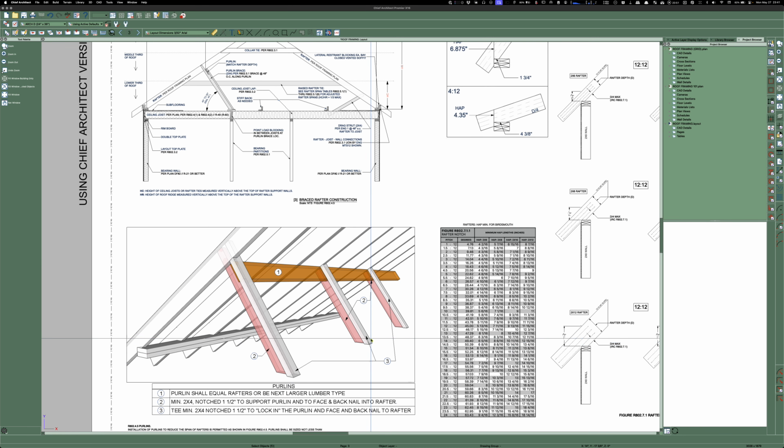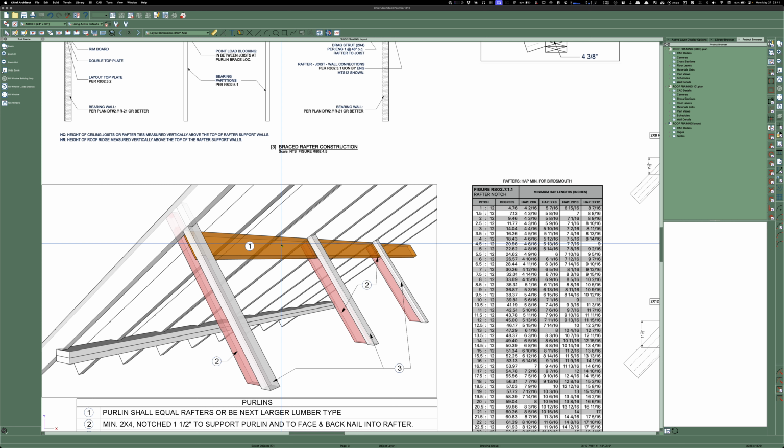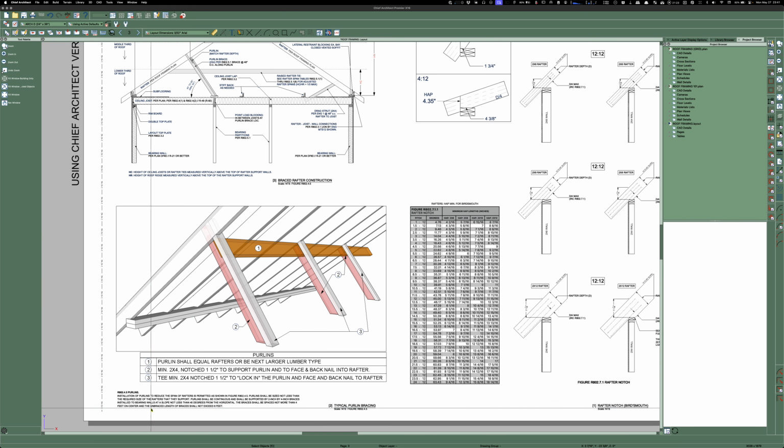And sometimes you don't have walls or anything sufficient that you can brace off of. So in those instances, you're allowed to go over to the angle of a 45. And you could tilt this pink one. You could nail it here and then angle it over and have it brace here. And then the other part of the code says you can't have more than 8 feet of the purlin just dangling out there, like over here. So you can angle these to go from wall to wall and stuff like that. Here's the code for that.